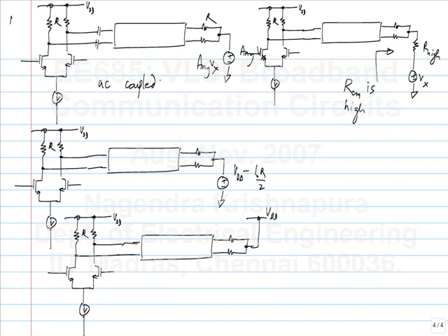So what does it mean for the transmitter in each of these cases? What is the best for the transmitter? Second one. Why? Okay, firstly, yeah, but that is true of not just the second one. If I call this 1, 2, 3, 4, first one has some low frequency limitation. You have to have this capacitance large enough to transmit the lowest frequency of interest.